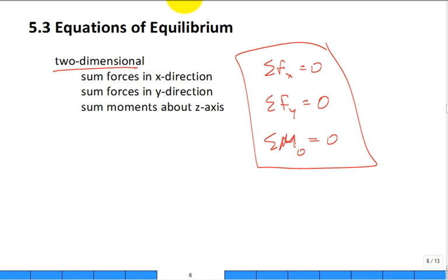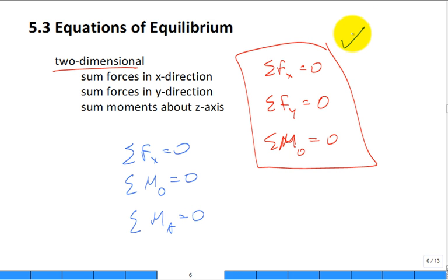In the textbook, it talks about how you can have three other unique equations of equilibrium. It would be something like the sum of the forces in x equal to 0, the sum of the moments around a particular point, the origin, equal to 0, and the sum of the moments around another point equal to 0. That'll work. But believe me, if you're the first time through this class or you just want to get the basics, this works 99.9% of the time.